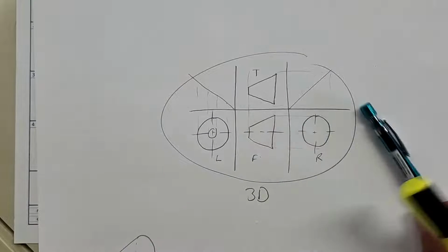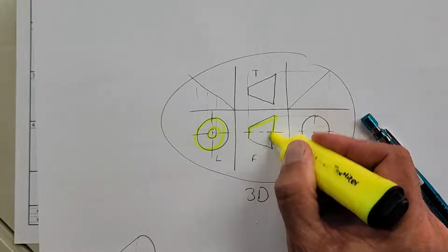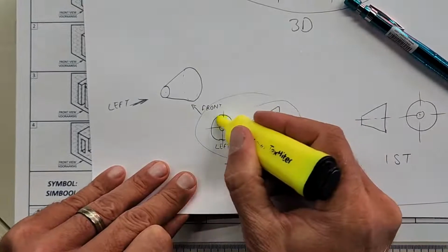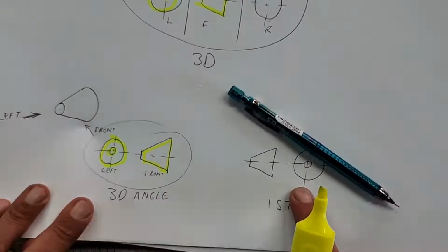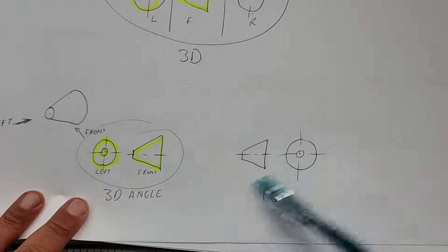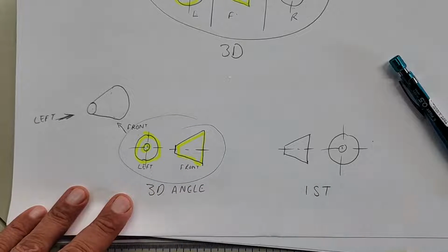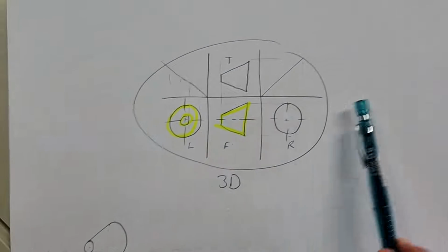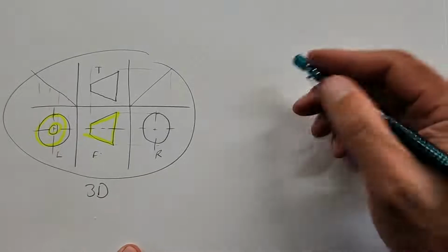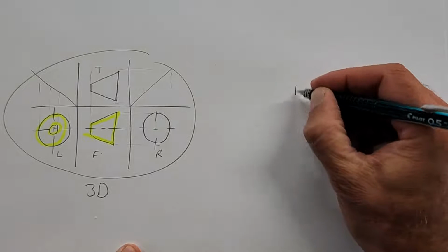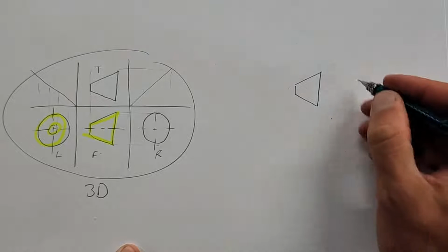They will always give you the left view and the front view. That symbol that we've looked at is made up by the left view and the front view. Whether it's in third angle or first angle, they don't show you anywhere else the other views. It's always the left and the front. And when it's laid out like this, it is the third angle. If it was first angle, we would have had our front view here. Where does the left view go now? Mooi so.